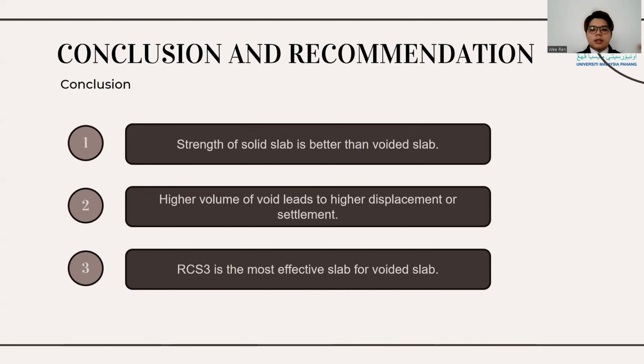For the result, it can be concluded that the displacement observed for RCS3 does not exhibit significant variation when compared to RCS4. At 8 milliseconds, the displacement for RCS3 is a negative 65.1 mm, while it is a negative 57.97 mm for RCS1, resulting in a percentage difference of 10.95%. The difference is still in an acceptable range. Similarly, RCS4 exhibits a displacement of negative 60.79 mm, leading to a percentage difference of 6.62% when compared to RCS3.